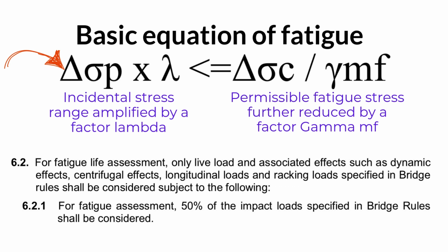Please note that as per Clause 6.2, for fatigue life assessment, only live load and associated effects, such as dynamic effects, centrifugal effects, longitudinal loads, and racking loads specified in bridge rules shall be considered. Please also note that, for fatigue assessment, 50% of the impact loads specified in bridge rules shall be considered.